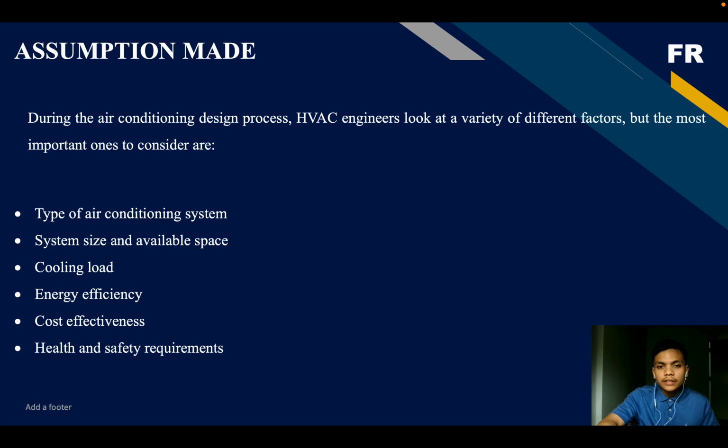During the air conditioning design process, the HVAC engineer looks at a variety of different factors, but the most important ones to consider are: number 1, type of air conditioning system; number 2, system size and available space; number 3, cooling load; number 4, energy efficiency; number 5, cost effectiveness; number 6, health and safety requirements.